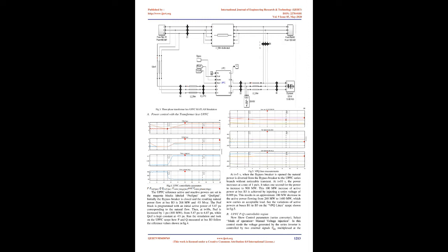The system, connected in a loop configuration, consists essentially of 5 buses, B1 to B5, interconnected through transmission lines L1, L2, L3. 2 power plants located on the 230 kV system generate a total of 1500 MW, which is transmitted to a 500 kV 15,000 MVA equivalent and to a 200 MW load connected at bus B3.